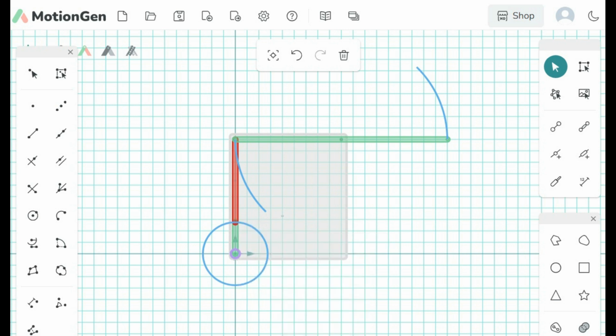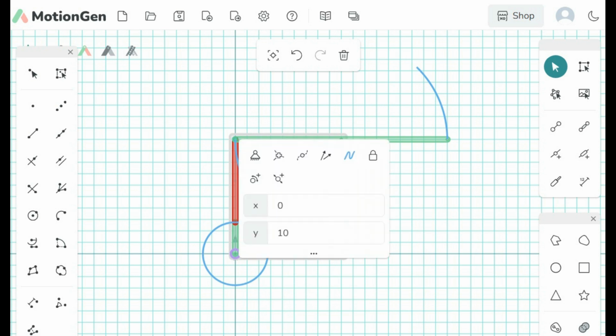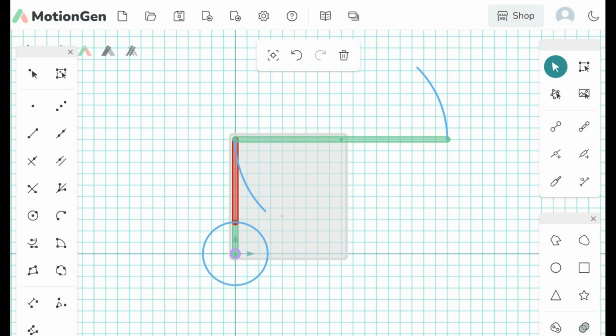Okay. Now we're going to change this connecting rod to 7 1/4. So the total is going to be 10 up here. So we're still okay there. Okay. Now we look, and the simulation icons are still there, so it's a good linkage.